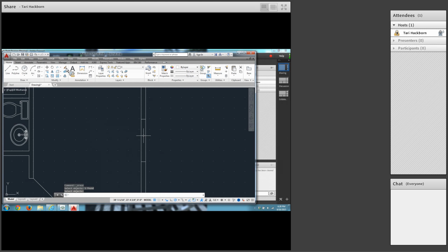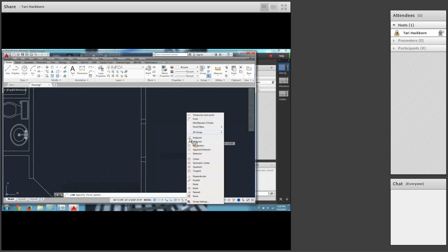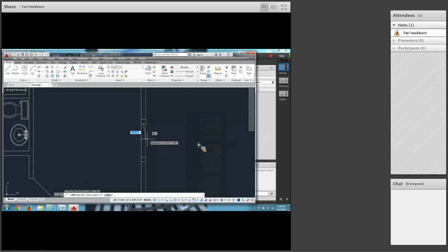They don't give you any specific instructions for finishing these windows, so this might be something you want to jot down. Each one of these short lines will offset 5 inches toward one another. So 5 inches toward the inside of the window. See, and I am clicking, and I'm clicking up, but I'm also clicking over. And then get your line command and do that old shift and right click thing, and from the midpoint of here, come down and you'll get a green X showing at the other end.